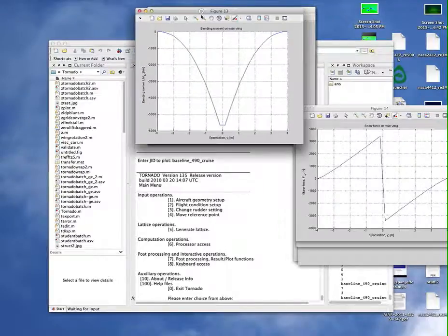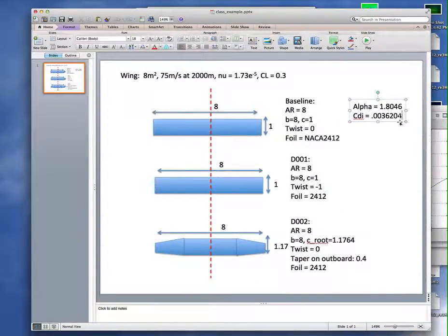Now I'm going to look at the next. This is the bending moment. This is the other thing you want to record. You have to count the dots, which I won't do right here, but essentially it looks to be about 5,700 newton meters negative, but I'll just record the absolute value. 5,700 newton meters. So again, it's a cantilever beam. Bending moment goes to 0 at the tip. Maximum at the root, magnitude 5,700 newton meters. Let me stick that in my PowerPoint.